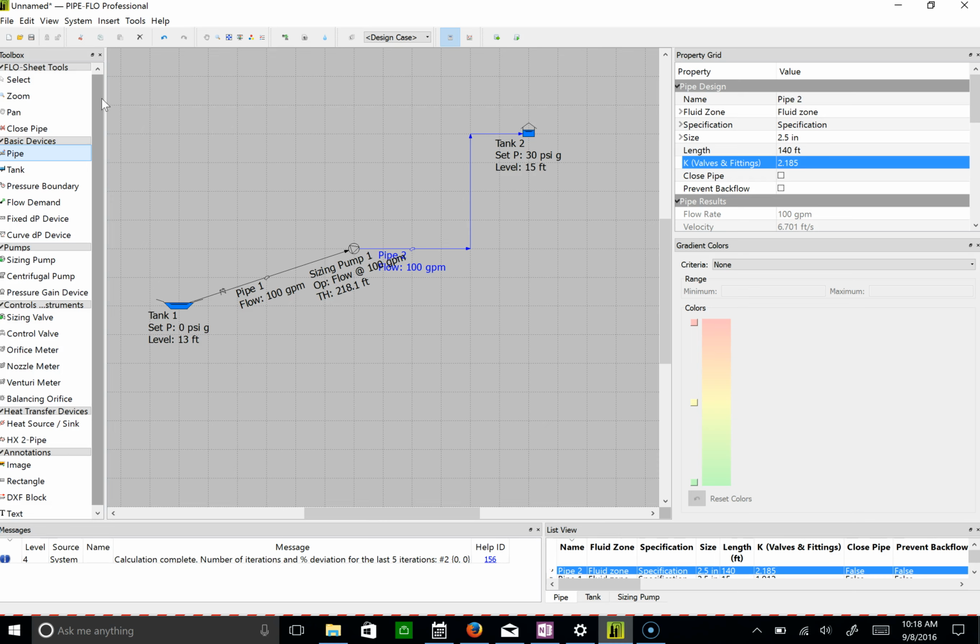So it just did the modified Bernoulli's equation for you. Isn't that crazy? It did it at least 5 times. Now look at TH. That's the head. At that volumetric flow rate, you get 218. Is that what the paper says? Or pretty close?